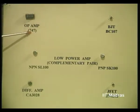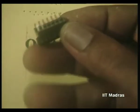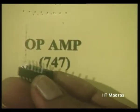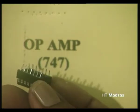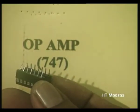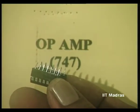The 747 comprises 2 identical operational amplifiers. Each operational amplifier has 2 input terminals, differential input, 1 output terminal, so 3 terminals, and 2 power supply terminals for the dual supply to be applied.